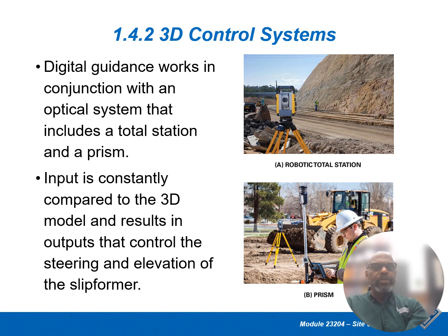So digital guidance works in conjunction with an optical system that includes a total station and a prism. Input is constantly compared to the 3D model and results in inputs and control of the steering and elevation of the slip former.